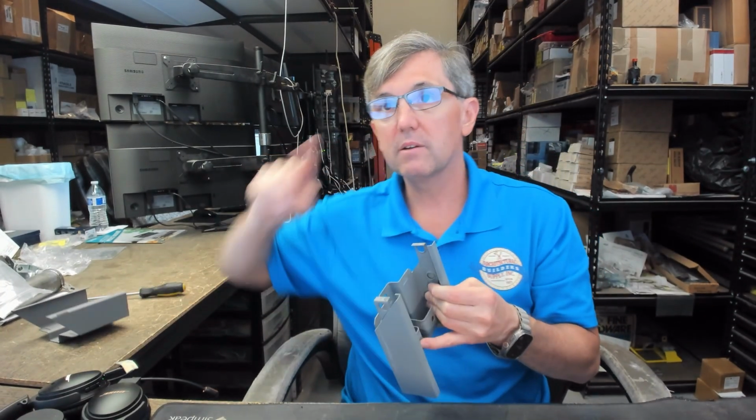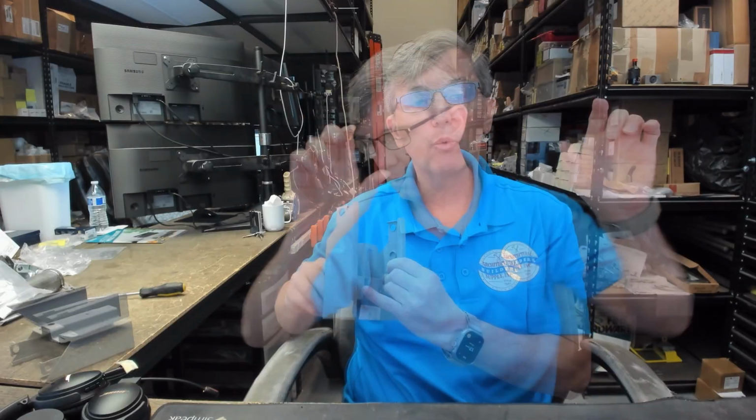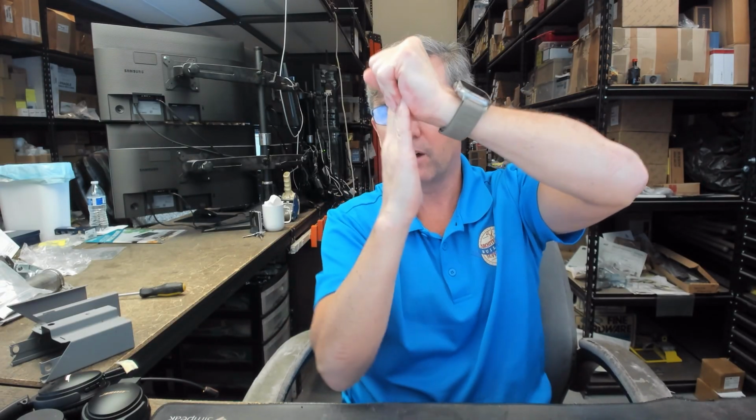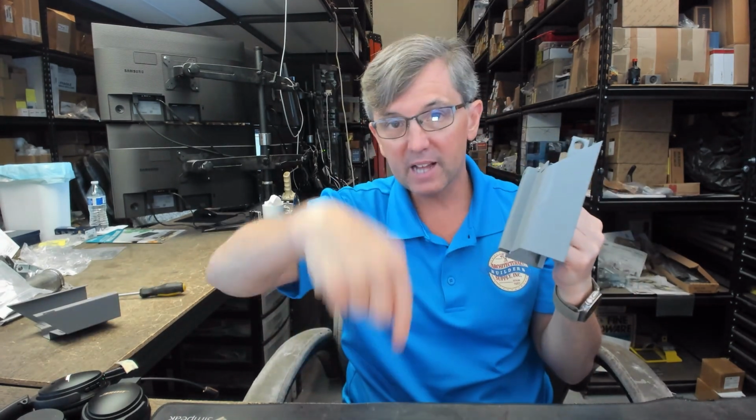You do that at the top of both sides of the jam to the point where you have a nice miter. Then you'll take the bottom of the legs, and all of this installation is inherent to drywall frames. You'll move that out so that you're true plumb, level, and square, and then in the face of the jam on each side at the bottom there's a dimple, and that's for a typical drywall screw that you run through the drywall into the stud.